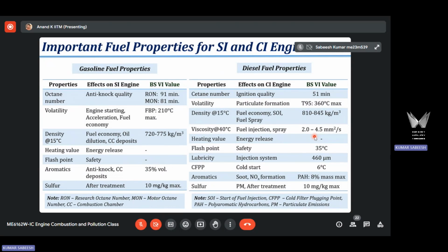So you are telling that if you play with that 10 to 20 degree, it will reduce that wall wetting phenomenon. Yes, that will have a more significant role. Once the piston is nearer to the top dead center, the bowl will take the spray. The way you design the bowl, hemispherical or any other bowl, I will talk more about it in the next chapter. Bowl design will play a role when the piston is nearer to the top dead center, but when the piston is far away from top dead center, bowl design has no role.